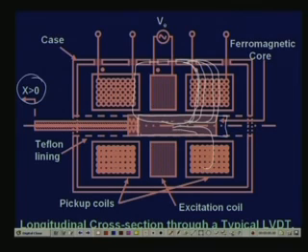Similarly there will be branches here, but when it returns, since these parts are non-magnetic, if it has to return through this, see here it's magnetic. So the overall reluctance of the path is limited to these air gaps, but if it has to come through this path, then it has to go through this much of air gap. So flux will not prefer to pass through such paths, but will pass through such paths, and therefore it will not be linking the second coil.